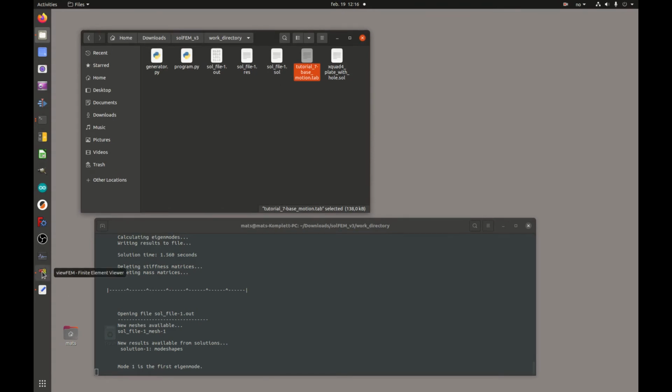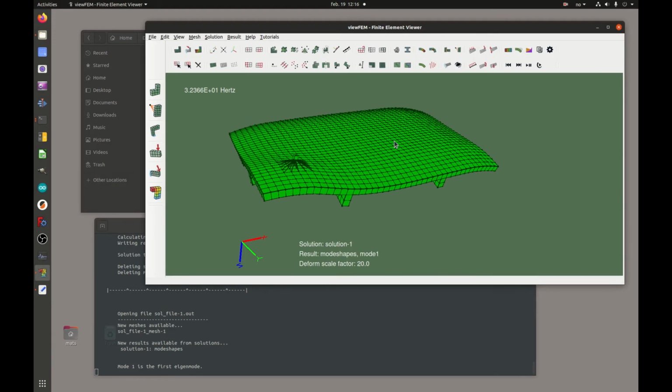So now that we have that input, we have loaded results here. We need to clear out the viewer before we start creating our Modal Dynamic solution, so that there's no chance of overlap between the results and the new mesh we are working on.